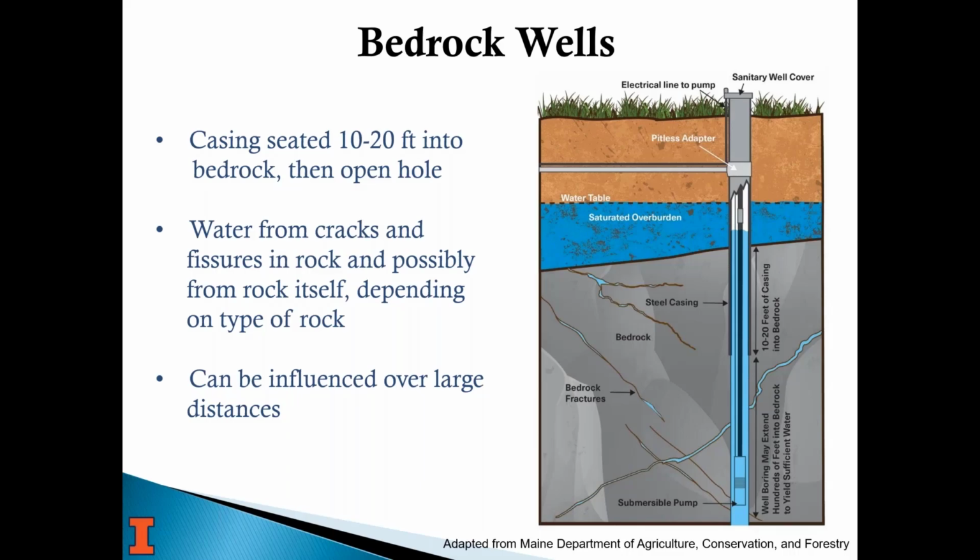And so in a 400-foot sand and gravel well, the only place water can get into the well is that last 4 feet. Like the example we looked at a minute ago, it wasn't 400 feet deep, but the well screen was only 4 feet, and it's the bottom 4 feet. Where in a bedrock well, this might be 30 feet into the rock total from the surface, and from 30 feet down to 400, water can get in anywhere because it's just a hole in the rock. And so it really matters, and that's why you need to understand those things.